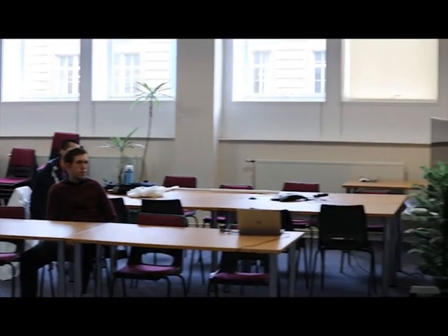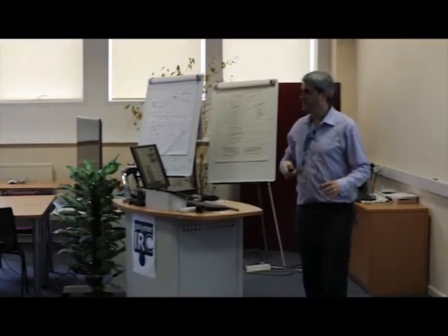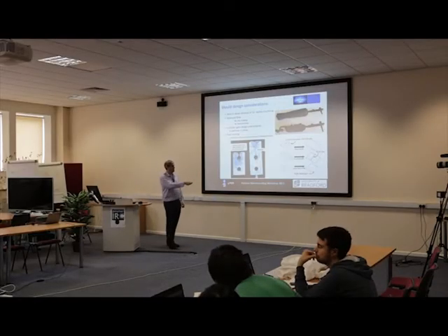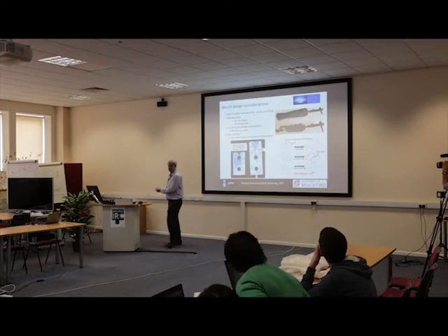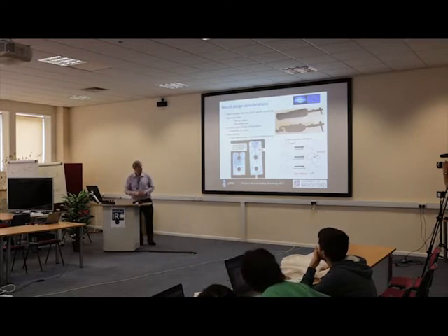So in many cases, we can't avoid these because if we have a hole in our part, there's no injection location on this part that we can choose that won't cause a weld line. But what we can do is maybe look at the FE modelling and make sure that these weld lines don't fall on really highly stressed parts or areas of the product, okay?